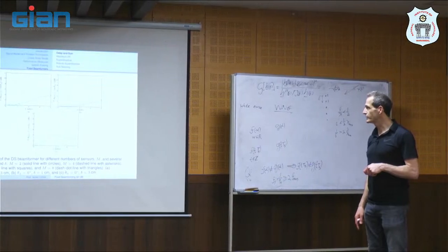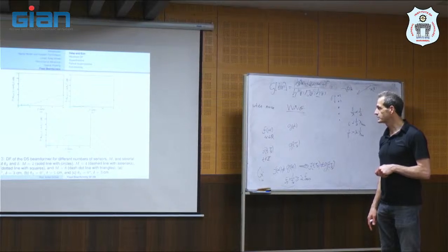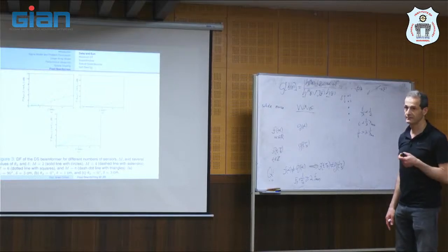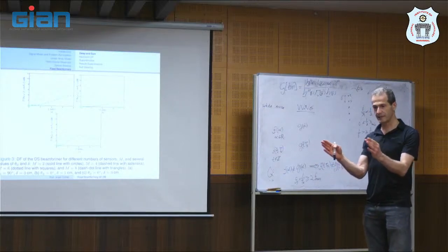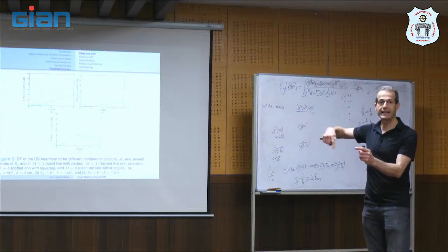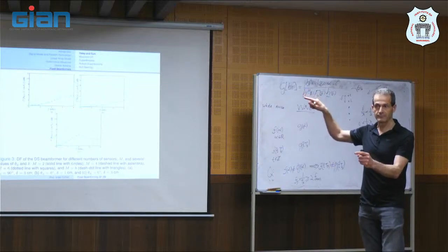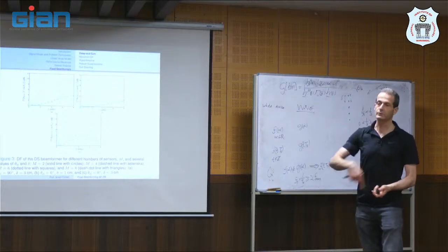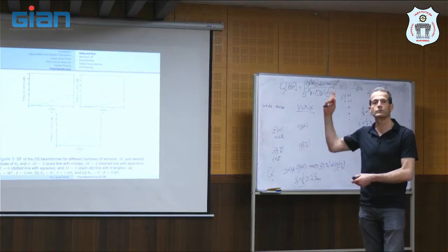So when you see a decrease of the directivity when the frequency increases, what does it mean? Aliasing. Because the main beam decreases, but then you start to get another side lobe from another direction that increases because of aliasing. And that's why the directivity decreases, because the integral decreases. Because you have a side lobe for a certain other direction that starts to increase.